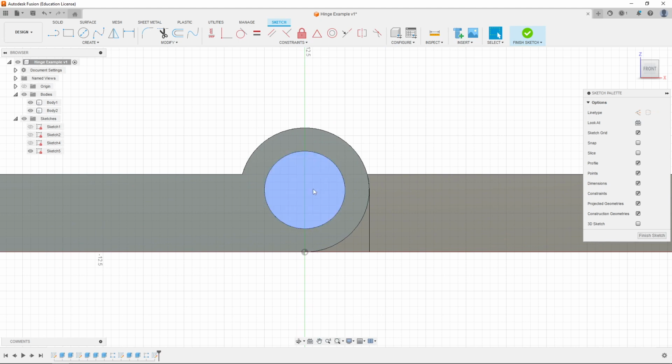If it were perfect, if we had a machine that did metal machining and it was flawless, then we might have no actual difference between the inner diameter of this circle and the diameter of the pin. However, because we are going to use a 3D printer and the plastic heats and cools, it's never exactly perfect, so we should always have some kind of threshold. And in fact, even professional machining tools also have some kind of threshold of perfection, a tolerance of how much difference there is, even if it's very, very small.